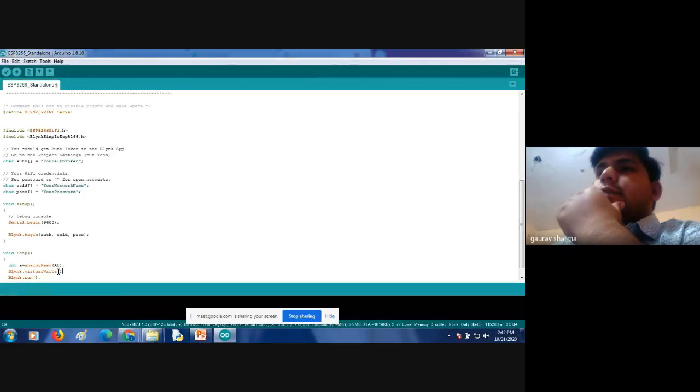After that, in the small brackets, you have to write the virtual pin number. Suppose you can start with 0, but I am taking virtual pin 1, and after that a comma and the value which you want to represent on that virtual pin. I will explain what virtual pins mean after this.